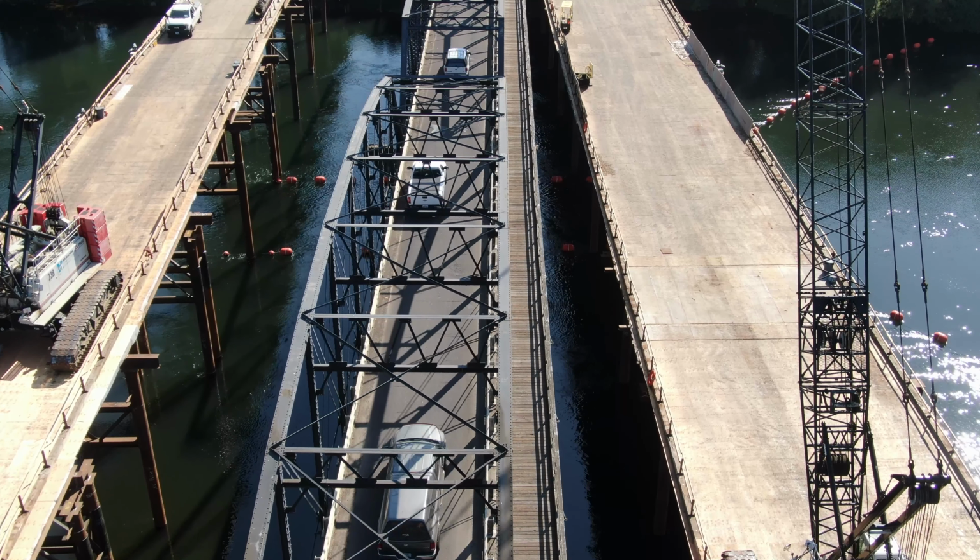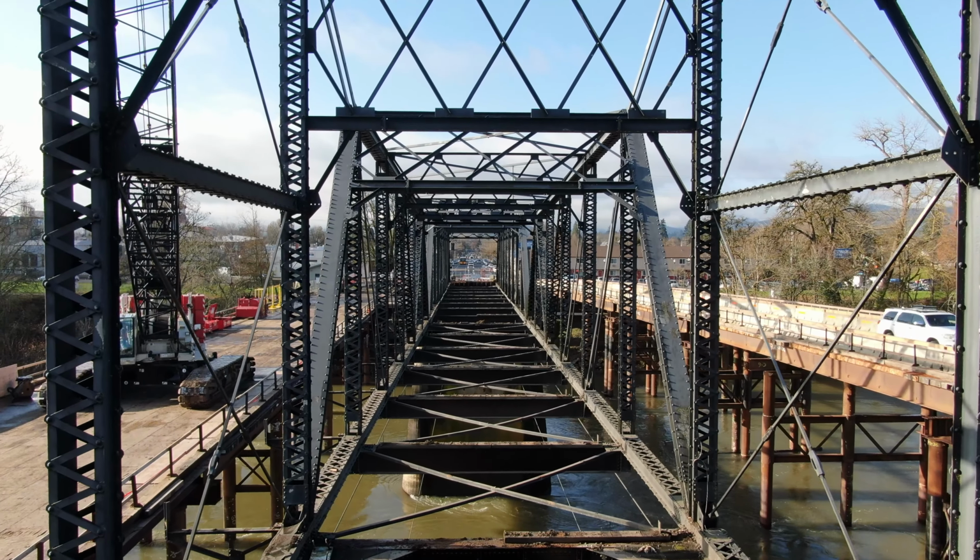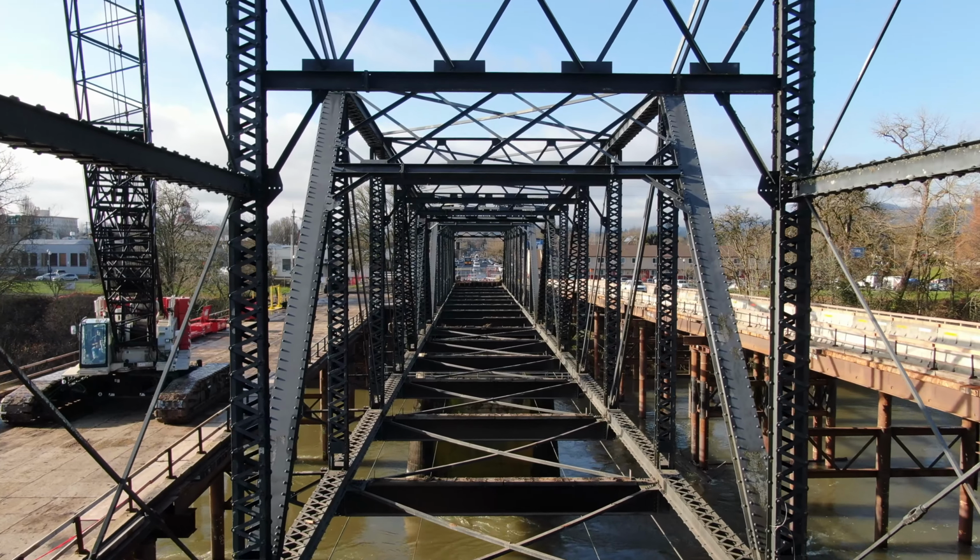Lateral load paths in a truss are there largely to resist wind forces. In the day that they designed these bridges, seismic was a linear design, force-based, and the lateral load system is X-bracings that occur in the horizontal planes. That brings the load down to the bearings in the lateral sense and keeps the bridge stable in the sideways sense. They differ quite dramatically, as I could see when seismic became more of an issue.